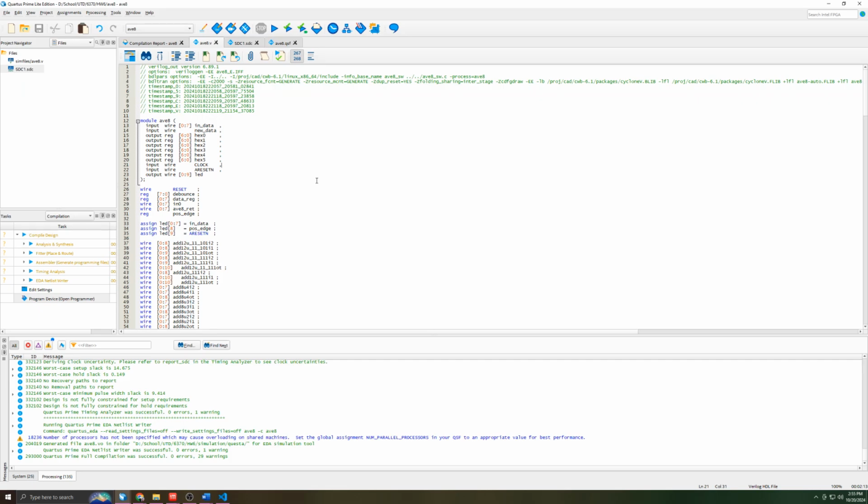And so now we're looking at the RTL code that was generated, and then I modified it to take user input data and drive the average number out to a 7-segment display. What I could have done is set up a wrapper that would send a clock signal every time the button is pressed, and that would basically accomplish what we needed. But instead of building a wrapper, I decided to just modify the code.